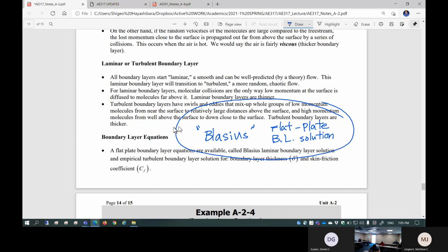Okay. So obviously XFLR5 is a panel method. Panel method really means that you're going to solve it without looking at viscosity. So the solution is all inviscid. If you want to incorporate your boundary layer flow over the surface, in other words, your flow starts laminar, transitions to turbulent, and then somehow separates, you are going to add a boundary layer model on top of it.